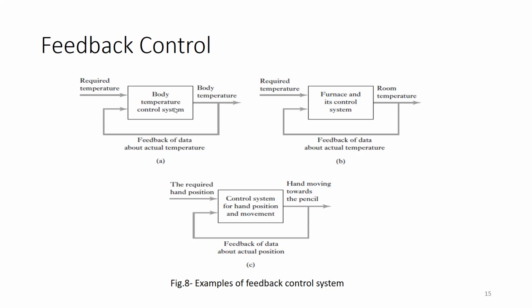So it is not matching, still required is 22, still it is 30. So it will trigger the control system to give more, you can say heat or coolness. Still more coolness is required, so the temperature should reach 22 degrees Celsius. Once it has reached 22 degree desired temperature, it will turn off the system, it will shut down the system.